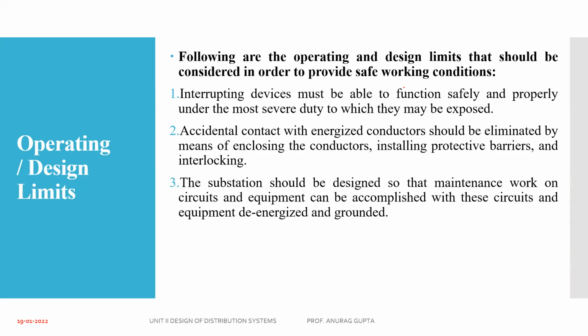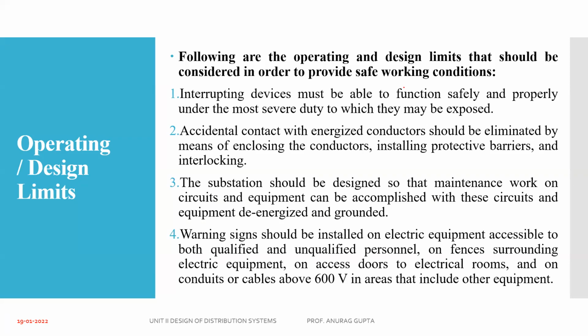The substation should be designed so that maintenance work on the circuit and equipment can be accomplished with these circuits and equipment de-energized and grounded. Warning signs: you have already seen, whenever you go to substations, some danger signs, voltage rating signs, or sign boards. A sign board must be at every substation where we are working with high voltage.